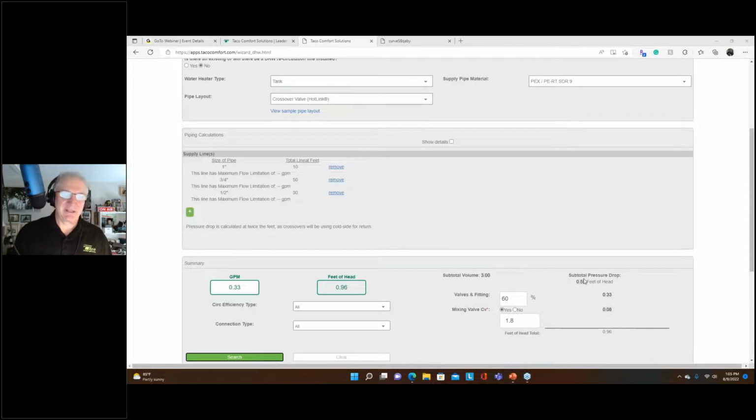So yeah, is the pump going a little faster? Are we over pumping? We are, but we have that. It's like putting that hot link crossover valve, George, is like putting a circuit setter on the system, is really what it's doing. Consider that a circuit setter. So even though the pump's running at its minimum speed, the flow is going to be 3.33 GPM because that's all that valve will allow.